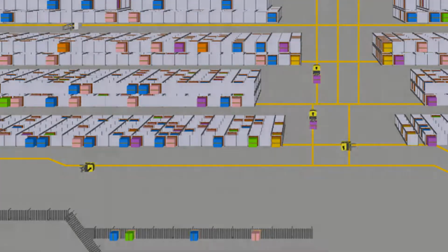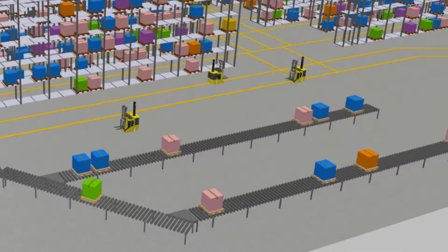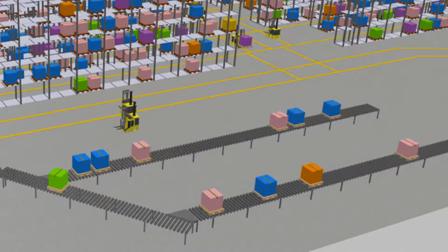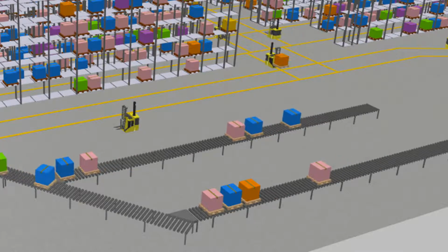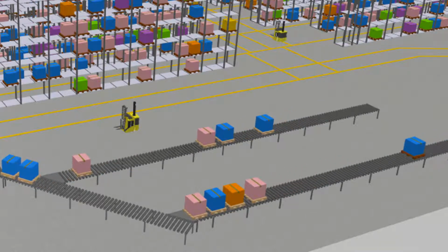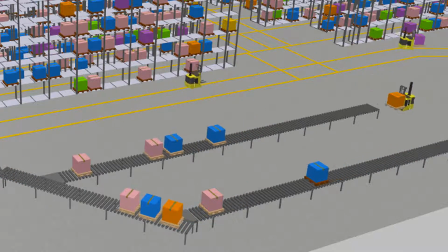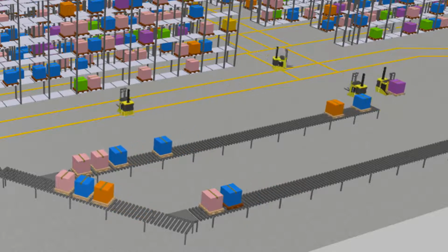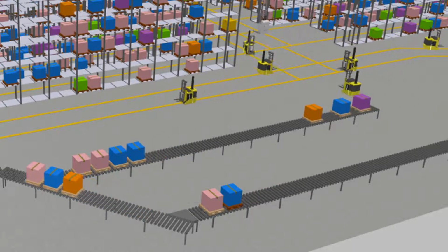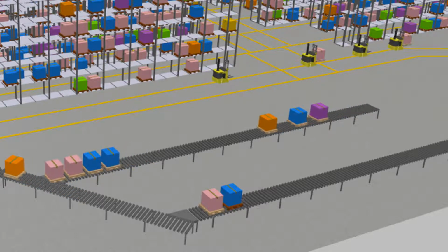So here you can see some of the conveyor merge logic at the south side of the plant. So you see we have 2 merge conveyors, and you can see the pallets are accumulating. You can also see that we're releasing a maximum of 3 pallets at a time, if you can recall from the input deck. You can also see we have kind of a cascading release structure where pallets wait for upstream pallets to clear and then piggyback behind them. So this is just a basic example of the type of custom conveyor and merge logic that you can code up and evaluate using simulation.